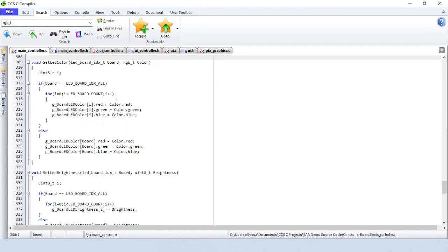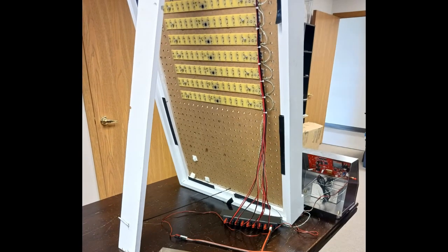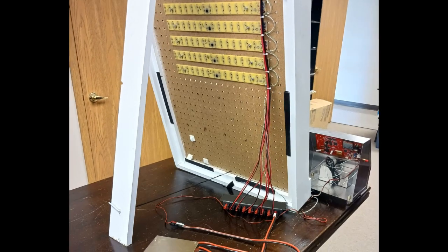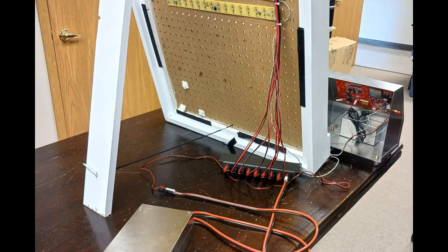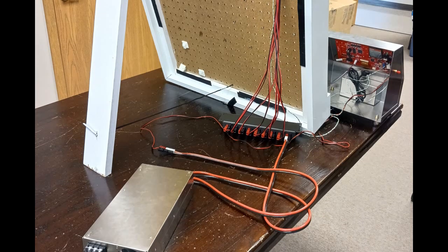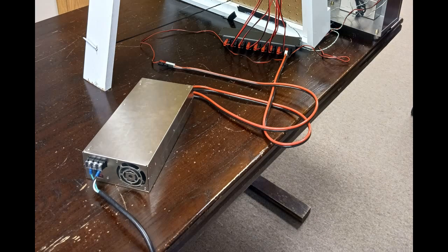There are 8 LED boards mounted to the wooden display. This picture shows the wiring in the back. Each board has 2 rows of LED lights. A modified version of West Mountain Radio's Rig Runner 4008H is used as the DC power distribution panel. Each of the LED boards are connected to the Rig Runner for power and to the touchscreen board for programming commands. The Rig Runner and touchscreen board are connected to a positive 5-volt 100-amp power supply.